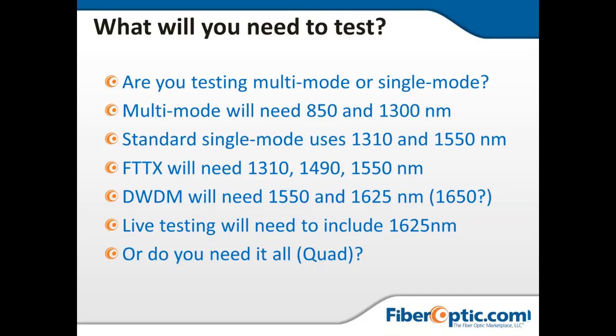Again, we're looking at the two wavelengths here because one of these wavelengths will be the wavelength that we will operate under, right? So if we're operating at 850, we want to know what the fiber looks like, how clean the fiber is at that particular wavelength. So we'll want to use that as one of the measurements.